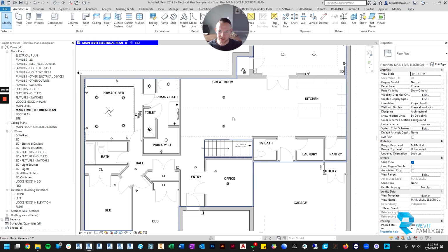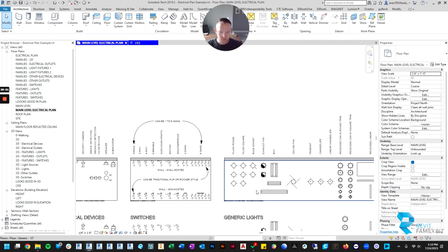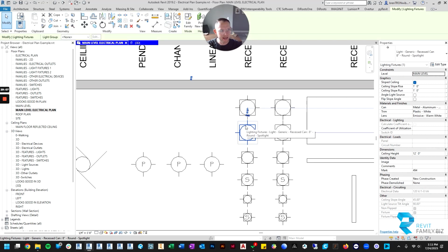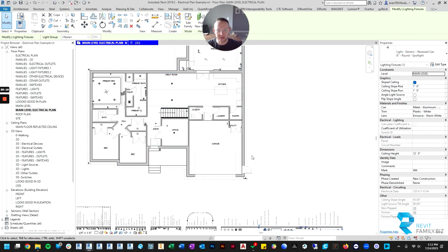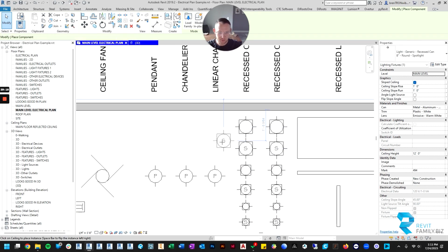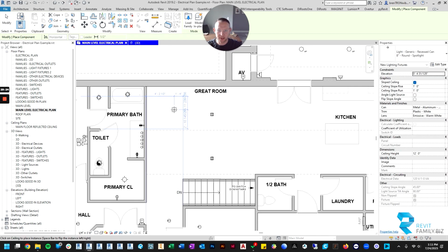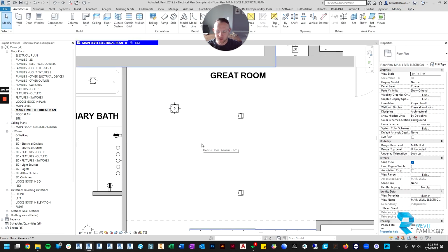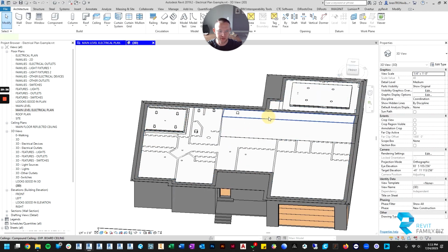Let's do the kitchen and the great room. So in the great room, we'll probably just do recessed lights, but maybe for these lights, we're going to go a little bit bigger. We'll do the 8-inch rounds, and we'll do the spotlights so that they can adjust, because the ceiling in the living room is a vaulted ceiling. So we probably want spotlights in here. Normally you would spend time doing the layout, but I'm just going to place my first one there. And then I'm also going to go to 3D, and I just need to see what the slope of this roof is, or the ceiling.